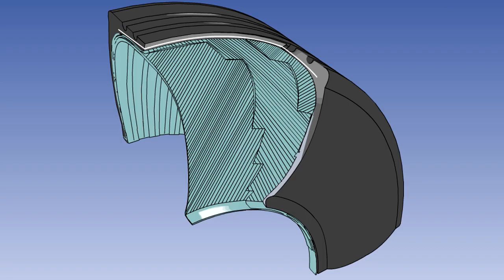You should now have an understanding of how the two types of tyre are constructed. Bear in mind that the ply rating of a tyre is not necessarily an indication of the number of plies. It is an indication of the tyre's strength. You also need to be aware of the effects of both under and over inflation of tyres.